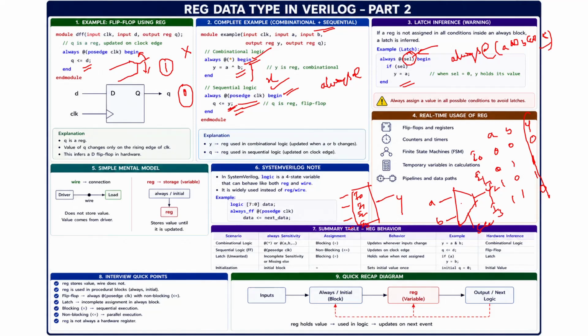So for I0 your output is 0, and for I3 the output is 0. So I0 and I3 are connected to ground, 0, and then I1 and I2 are connected to high voltage 1. That is the XOR gate representation.